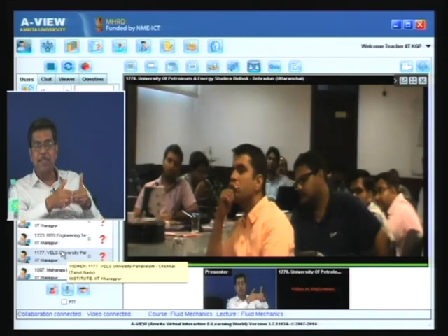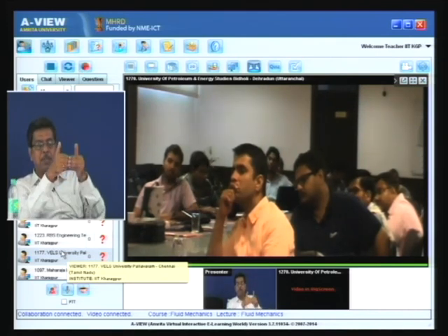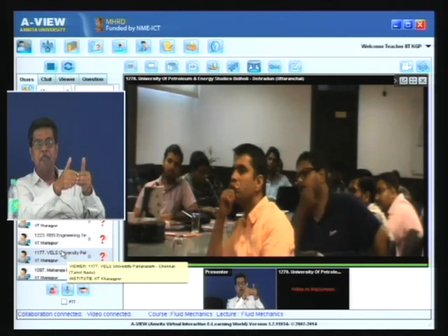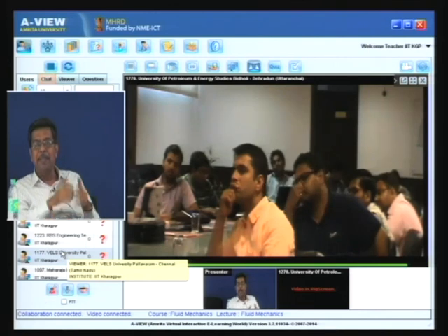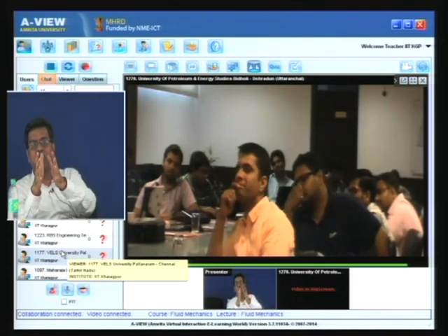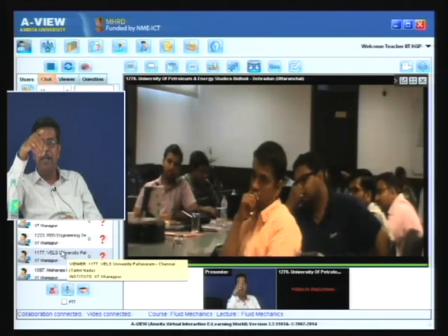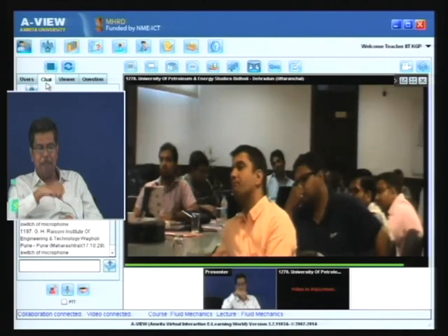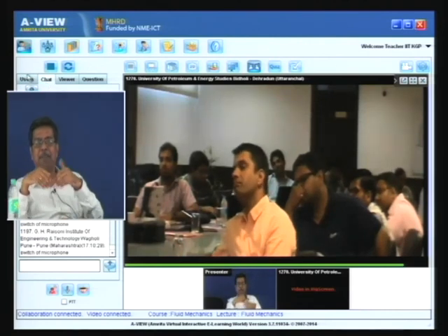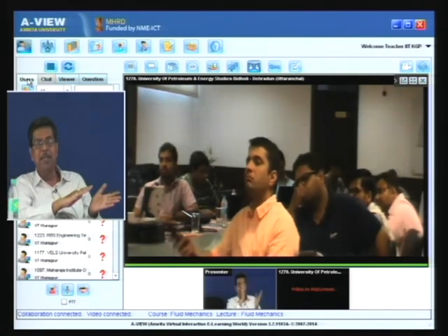All this information regarding the conservation of energy, momentum and mass of the system is known, and then we apply it to a control volume where the mass fluxes are there across the boundary, and due to this mass flux all these properties are taken away or coming in. That means property fluxes are there because of the mass flux. Energy is coming in, energy is going out, momentum is coming in, momentum is going out. Then we relate these two things.